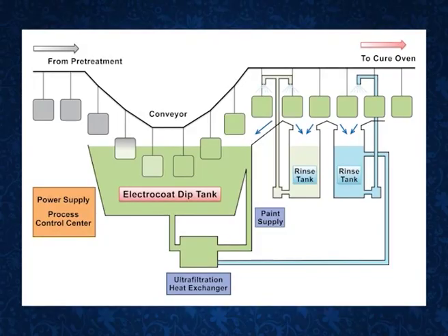Paint layers in case of automobiles. Now, the most common types of paint examined in the crime laboratory are finishes from automobiles. Most cars have 4 coats. Some luxury cars have more than one top layer coat. The organic coatings used in case of automobiles comprise an Electrocoat Primer, Primer Surfacer, Basecoat and a clear coat. Let us discuss in brief about them.